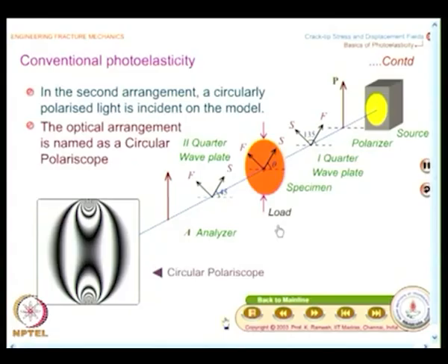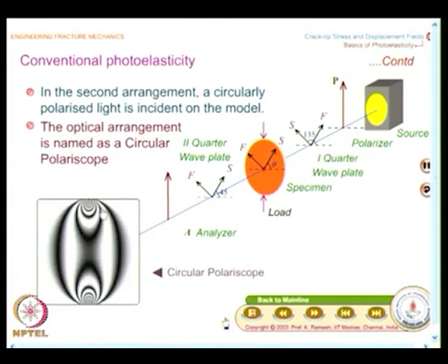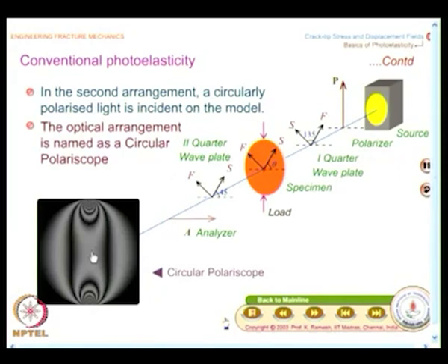And what you have to notice is that in the experimental fringes, the thickness varies. If you see here, the thickness is very broad. When you say a contour, you will have only a line. What you have to do, where you are plotting the fringe order, is give a small variation and plot that analytically, and you will automatically get a thickness variation. You have papers written on that, you could look at the references. So, if you know sigma x, sigma y and tau xy, it is possible to plot.